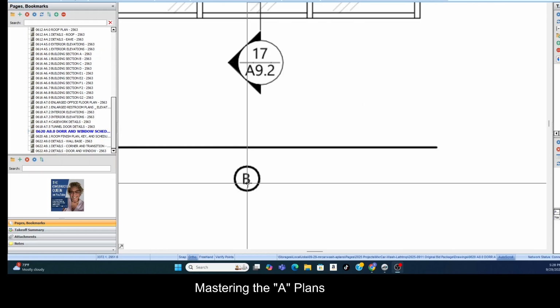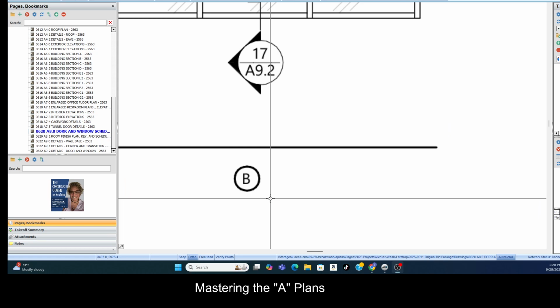So if I had a hotel, a 5-story hotel, and they all have B windows, how do I know how many B windows I have? I know how many doors I have, because even in that situation, each door is individually marked and named, but not with windows. So in that case, you'd have to look at the exterior elevations. That's where you see the windows, and they'll have a B on it, and you have to count it. You have to do the counting on windows.